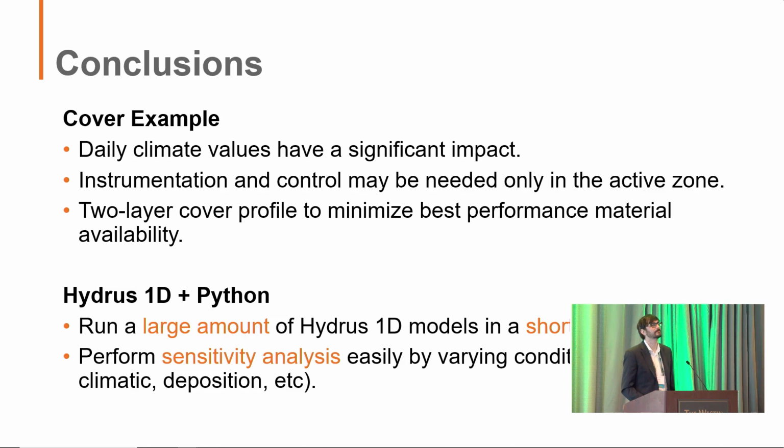I'm just wondering, how did you calibrate the model to existing conditions? We can use instruments, as I said before, at the top of our cover to understand if, as time goes by, the degree of saturation is similar, right? We use a lot of parameters inside of our material properties, hydraulic properties, and that's a way of doing it. Okay, thank you.